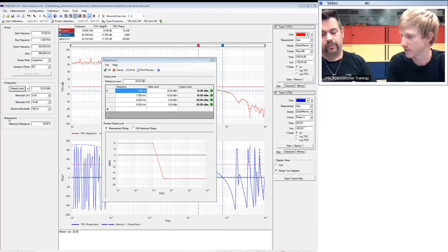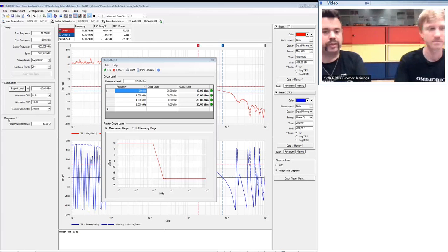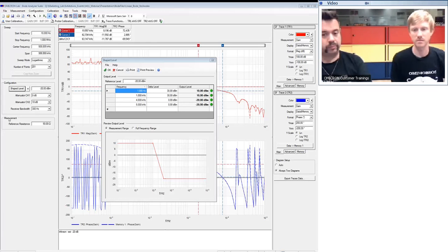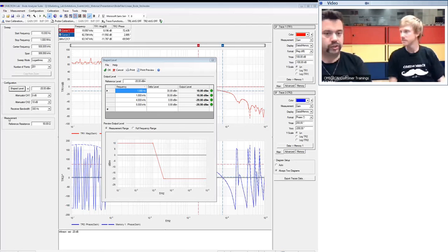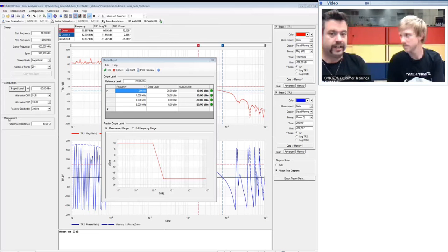We first found out that minus 20 dB is the perfect level where there is no longer an influence on the phase margin, on the point where the amplitude gets below 0 dB. The gain goes below 0 dB. Then we said, okay, but now we have this noise, and therefore we just increased everything which is below this pass-through point.